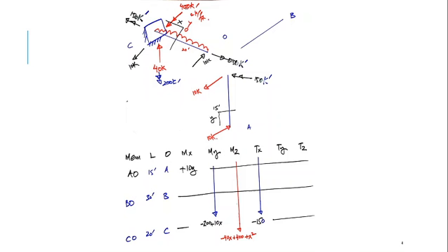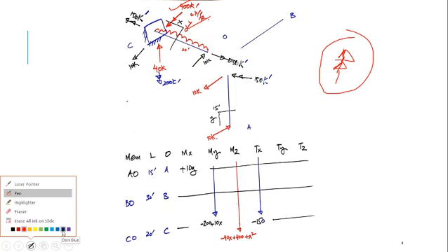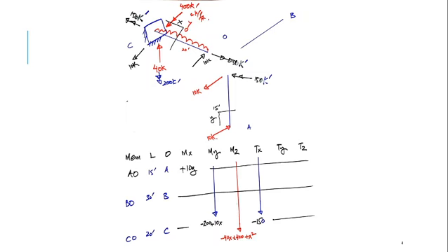Now coming on to this 400 kip-foot moment, this is in Z direction and this is anti-clockwise. It should be balanced with a clockwise in Z direction at this point, so that would be 400 kip-foot, and you should know that this is now clockwise, this is anti-clockwise. It should be written here in MZ because this is applied in Z direction.